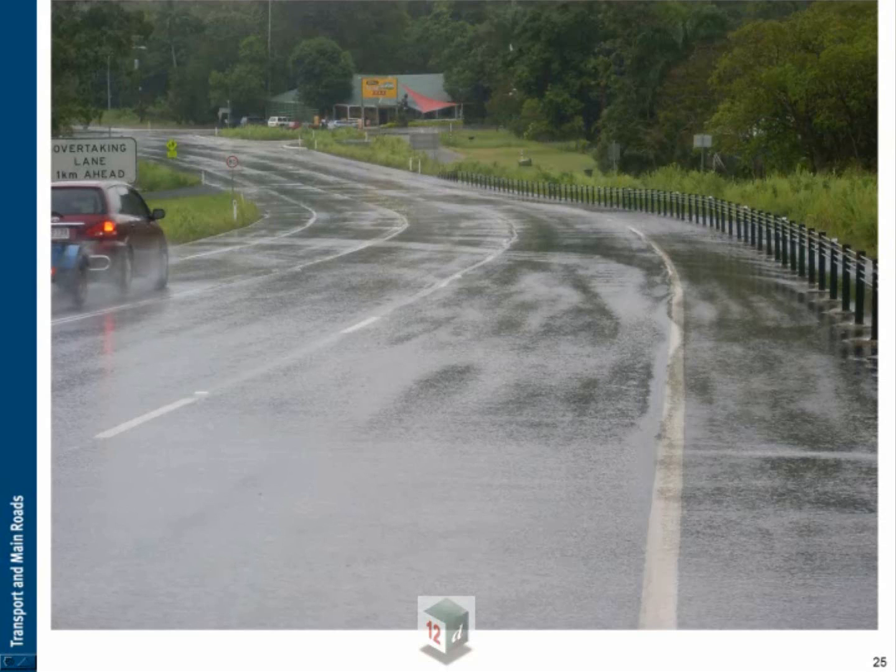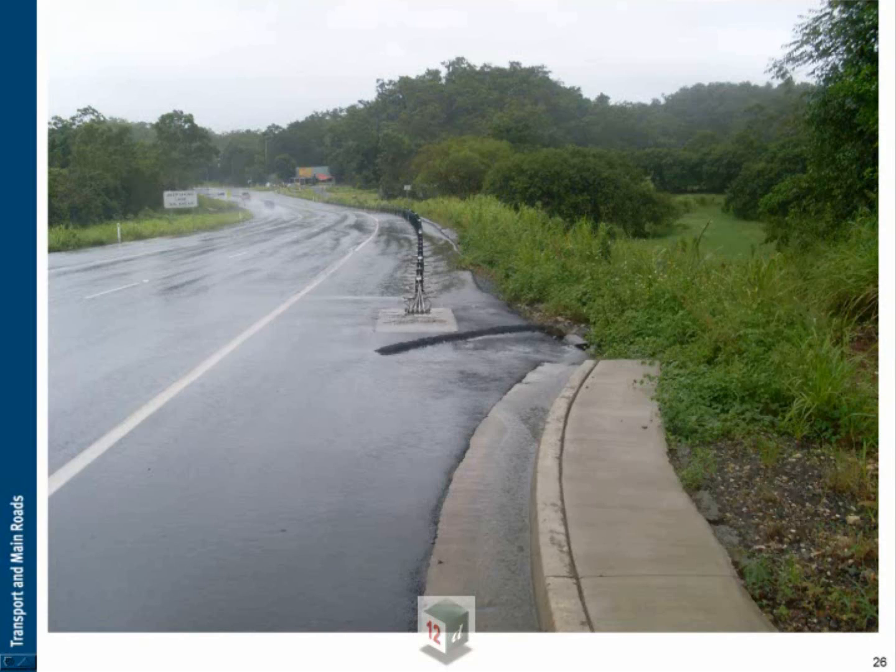If I step back a little bit, you've got this drain. This is coming down about 7 to 8% slope, standing behind the photographer. Most drainage would come down and then swing to the right and go off to that little turnout of water. They've even put a little bit of an asphalt levee there to try and catch some of that water and get rid of it. If you look ahead to the wire rope, you can actually see a bit of a sheet flow across it and how it's starting to turn and head back left.